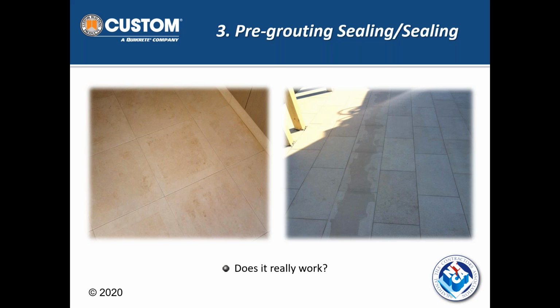Well, what happened there was they did pre-seal it and realized, hey, this works great. It helps everything that we had talked about. This is great, fantastic. They had a guy on the left with a roller rolling up to a certain line, and then the guy on the right rolling up to a line, and they missed it by a row. So again, did the sealer work? Sure it did. Now you can see what would have happened to the stone. By the way, that was a modified epoxy grout on that job.